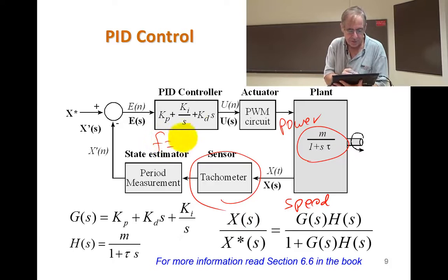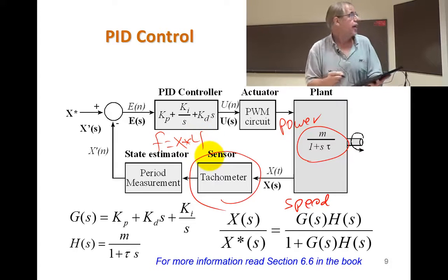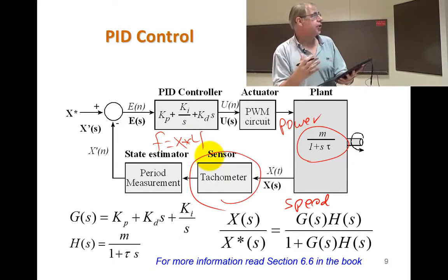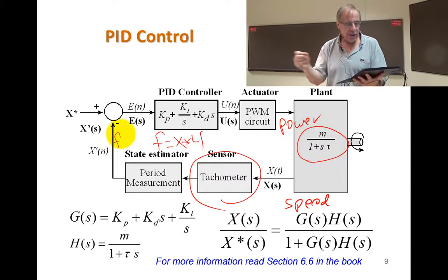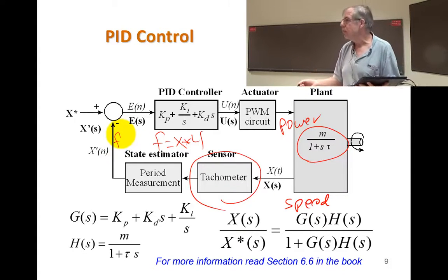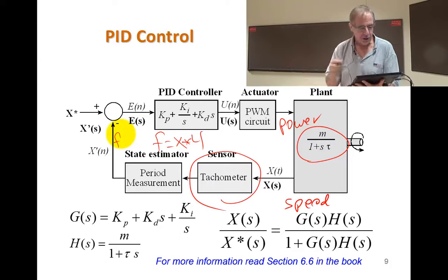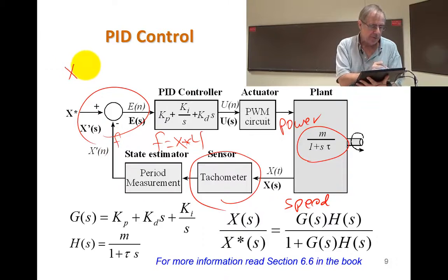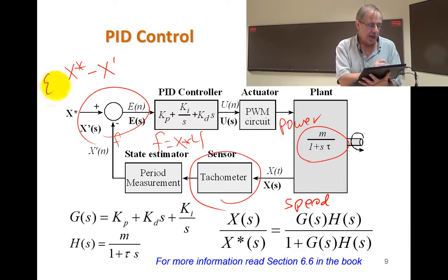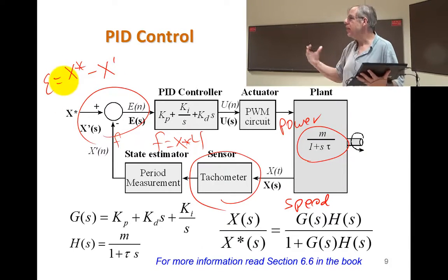That F equals, I'm going to call it X, times 4. So that's the behavior of our tachometer system. The frequency measured here is a linear function of the speed. So again, that's a linear function. The subtraction function, we're going to take the expected value, the desired value, and subtract off this measured value to get error. That's a linear equation.